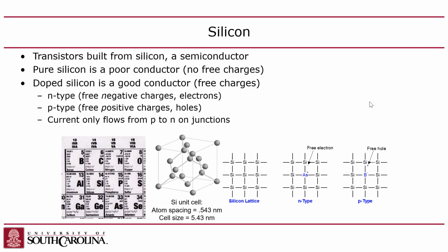The more you dope it, the more conductive it is. You can choose how many of those atoms you want to replace with dopants. It's up to you. If you put in a group 3 element, that's called p-doped silicon. P standing for positive. Why positive? Because there's a hole. A hole is a lack of an electron, and electrons are negative. So if you put boron in there, it becomes p-doped. And if you put in something from group 5, like arsenic, everyone's favorite element, then it becomes n-doped silicon, with negative charge carriers, right? But either way, it just becomes conductive.